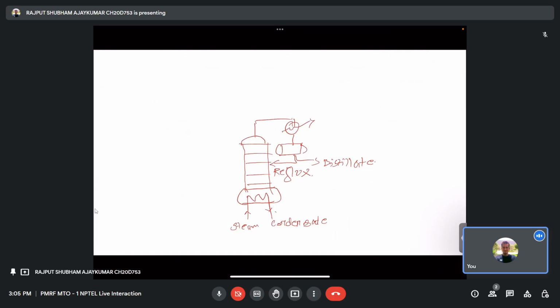As we said in the last classes also, batch distillation is considered an unsteady state process. However, we assume that a pseudo steady state condition prevails because of the contact of the gas and the liquid. This means that the liquid and vapor concentration profiles in the column at any moment are the same as the steady state profiles achievable under identical conditions. So it is easy to understand that if the reflux ratio is held constant, the distillate concentration will decrease as the distillation proceeds. The column may be operated till the distillate quality remains within the acceptable limit. This is what we call batch distillation.